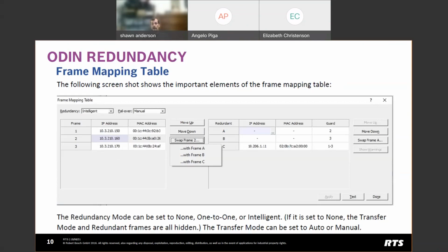And there are a lot of different features within here where you can set what it swaps for. You can put priorities to these. If you have it set to back up more than one frame, it will default to the lowest. If in the case of, say, you had 2 frames go down, pretty unlikely scenario, it will default to the lowest number frame first, and then the next highest, and so on and so on. Now, some of the unique features, if you're running the redundant systems, is the fiber interconnect link, the IFL, does not need to actually be in a certain topology.